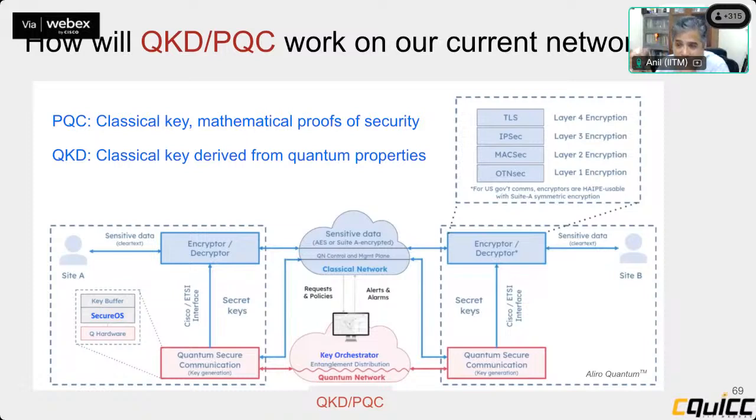So there is this factor of 1,000, where the receiver is 1,000 times more sensitive in the case of a quantum link. Because the receiver is 1,000 times more sensitive, we can make the transmitted power 1,000 times weaker. That is primarily it. After that, it's a lot of interpretation of how we are transmitting. Most classical communication today in India, at least on fiber, is just on-off keying. 1010 is just on-off keying, like I had shown you. But quantum communications is not using on-off keying. It is using more of phase or polarization.